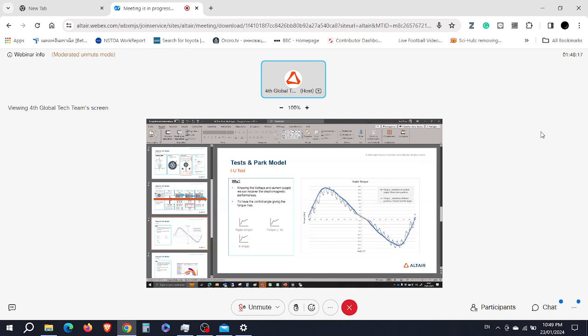And this static curve will not take into account the spatial harmonics. So if you impose the current and you vary the rotor position, you will see the impact of the slotting on your torque, on this static torque. So you can see this spatial harmonic.